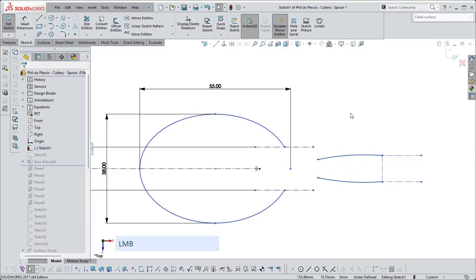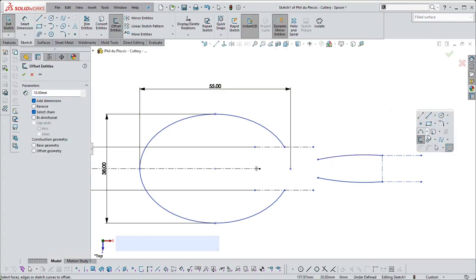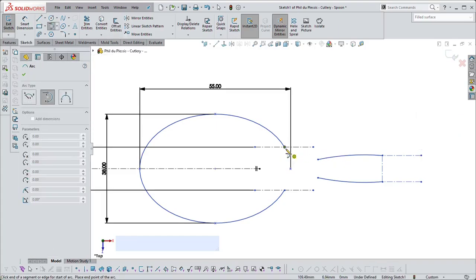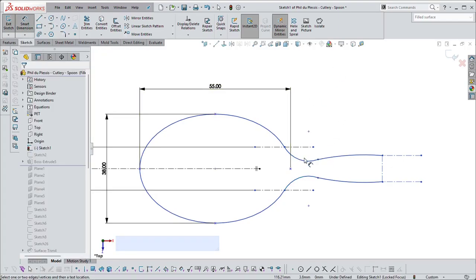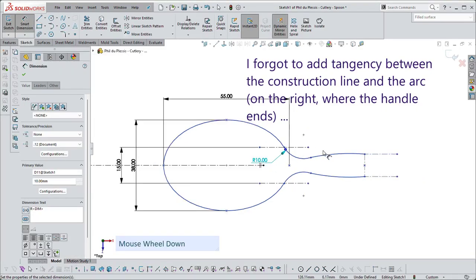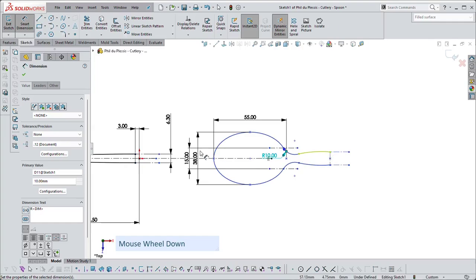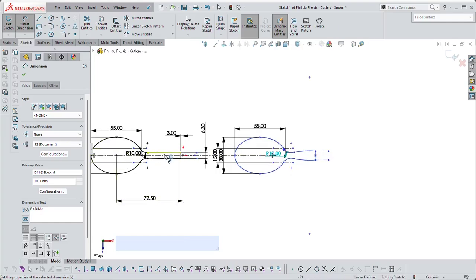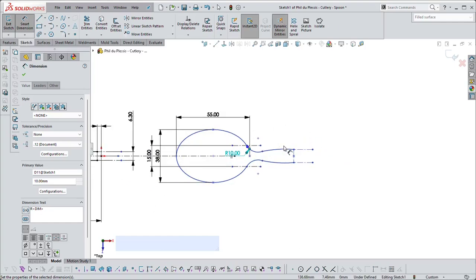And then the last one, you won't be able to put in a fillet. You'll have to use the tangent arc. The fillet won't work because you have an ellipse going all the way around, and it won't know which point of the geometry to choose. So there we go. I've got tangent arc, and the moment I dimension this, I can start controlling what it does. So that's the basics of how I got this right. So the rest of my sketch goes dark because of that dimension and that dimension, which I'm not going to put in over here.